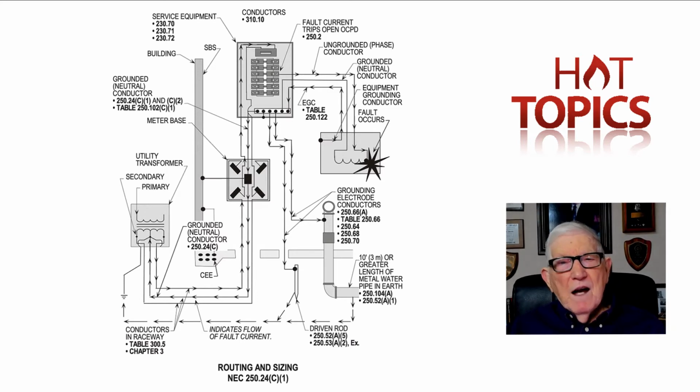And I have to check it to see if there are more phase-to-phase loads without neutrals, or more phase-to-neutral loads with neutral connections. And that's what 70B tells us. That's one way to check your circuit mapping, if it's been identified properly.